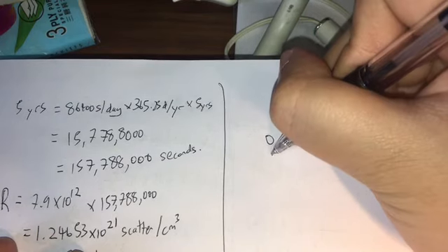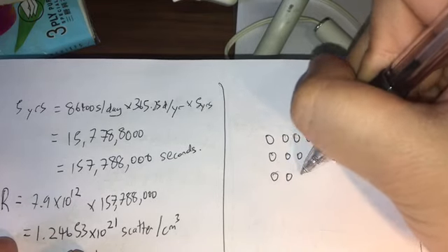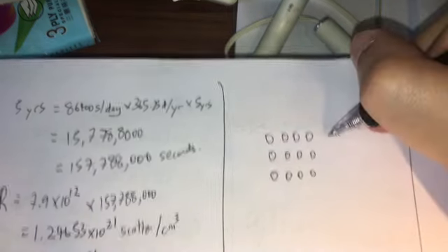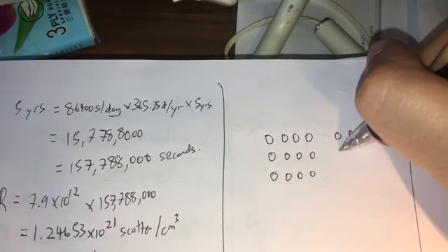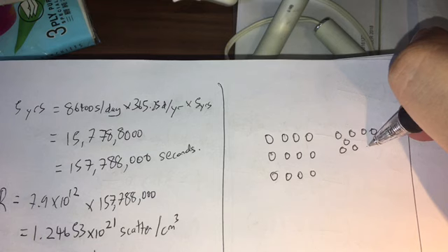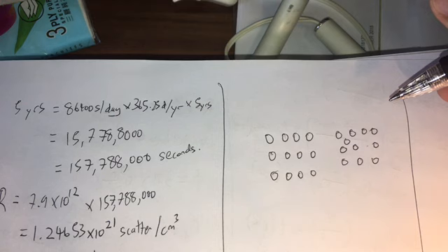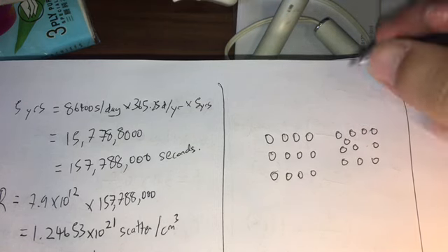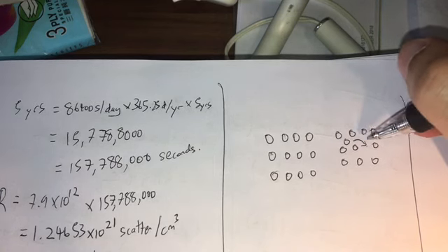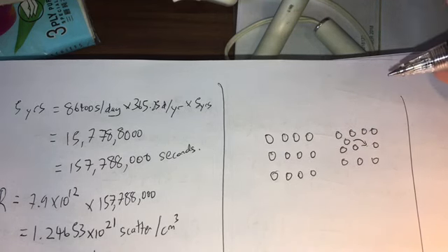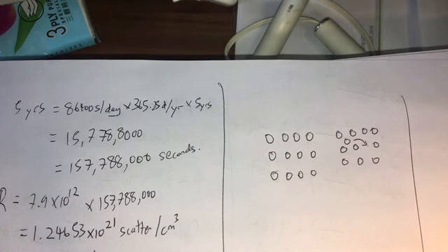let's say you have this lattice. Before the neutron messes it up, and after the neutron messes it up, we will have some vacancy and interstitial pair, which is this Frenkel pair here. Well, why doesn't this material just get destroyed? So sometimes the vacancy and interstitial can recombine and release heat, and in that sense the damage is negated. So that's what happens for many of these vacancy and interstitial pairs or Frenkel pairs.